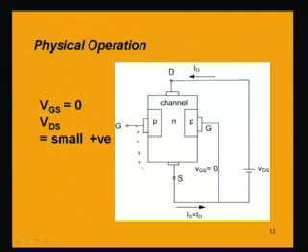Actually, there is a common connection between these two p's, but instead we are just showing a gate terminal here also. This is also the gate terminal, because these two p's are connected by these two metal contacts, and this lead connects between them. So, these two p's have the same gate terminal, described by writing a G here. This is also G, this is also G.